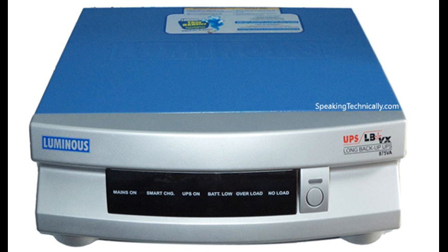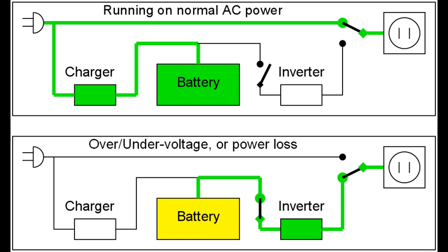One very common use for inverters is in emergency power supplies, also called uninterruptible power supply. If your household power fails in an outage, one might have a UPS as a backup. A typical UPS stores energy in electrical form using rechargeable batteries. When the power is flowing normally, the batteries are being charged by DC, which is produced from the AC power supply using a transformer and rectifier circuit.